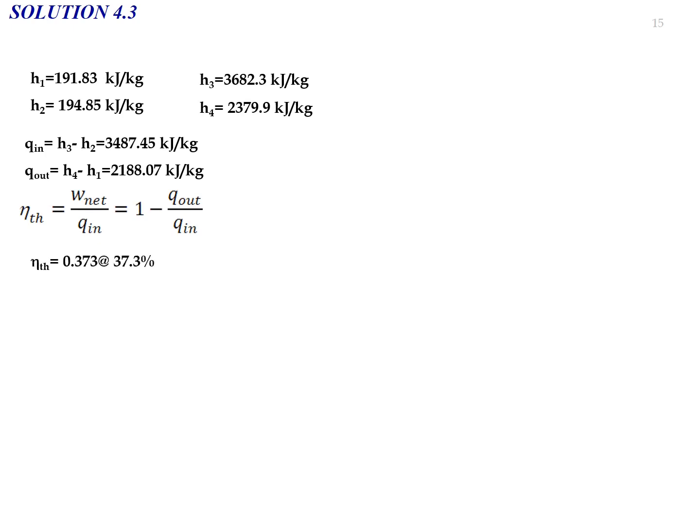So we have the new thermal efficiency for question B, equal to 0.373 or 37.3%. You need to compare with the thermal efficiency that we obtained in question A. The thermal efficiency for question B is greater than the thermal efficiency of the Rankine cycle for question A.